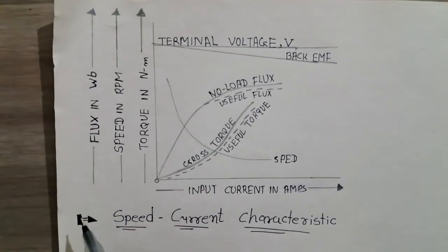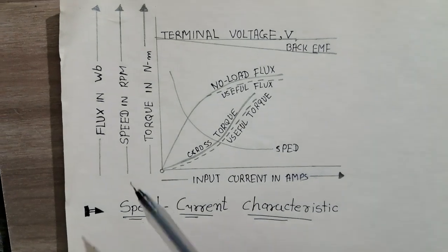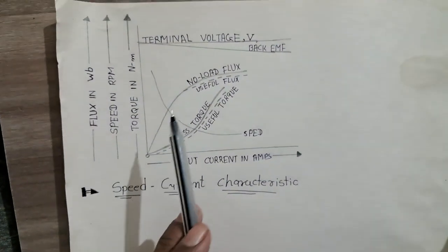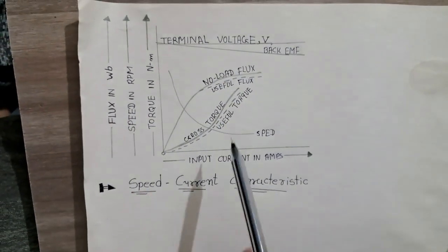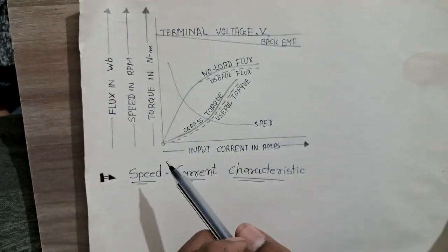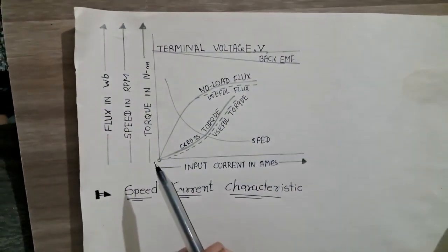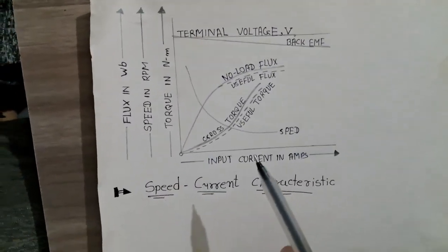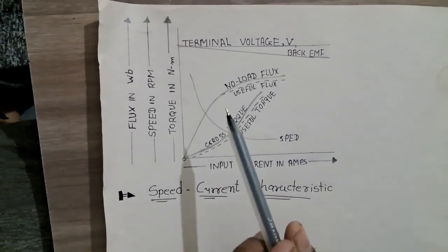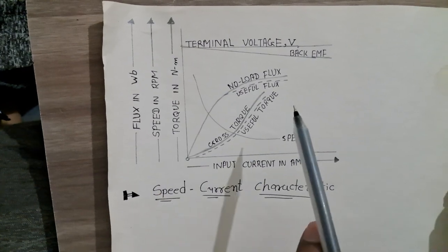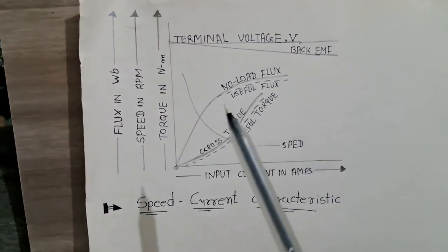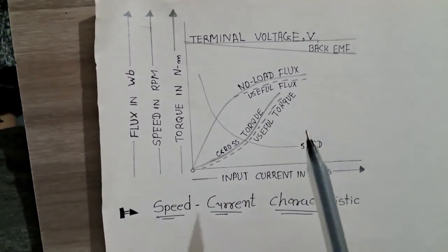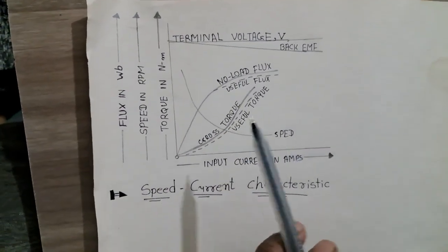The theory is that the MMF due to the exciting coils increases in direct proportion to the line or armature current. So the value of flux varies with the load current according to the ordinary magnetization curve. Owing to armature reaction, the actual curve representing the useful flux falls below the open circuit magnetization curve, as shown in the figure. With larger current, the magnetic circuit gets saturated and flux phi tends to approach a constant value.